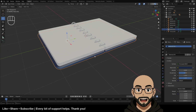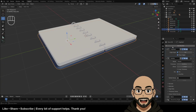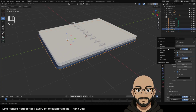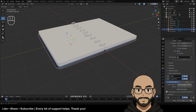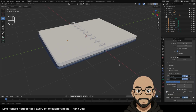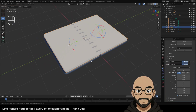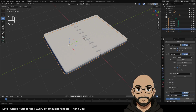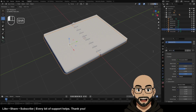If you want that to be a lot smoother, you can see here it's really sharp. You can add additional modifiers. You can go here, add a subdivision, or you can try to clean up that edge loop. But yeah, there we go. I think that'll work. So we've got the cover material. I can call this notepad cover.